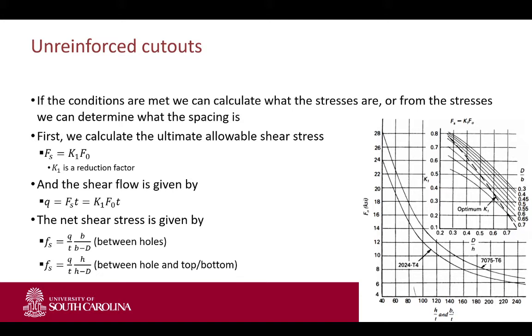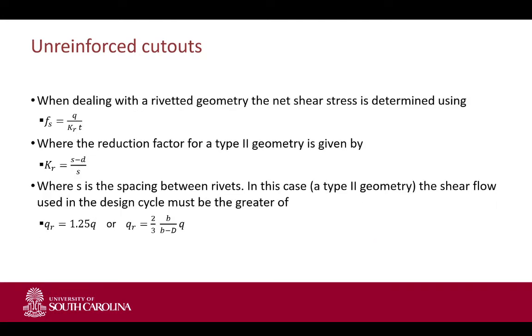Okay. And then you can also see how the stress concentration affects your shear flow, and based on your shear flow, the net shear stress. In this case, they use F, and I maintained the same variables they use in the NASA report. So you can see how the shear stress between the holes, and between the hole on top and bottom, varies based on the hole diameter, the height, and the thickness. And of course, if you have riveted cutouts, you have to take into account the stress concentration on a rivet. So again, it's the same procedure that you have to apply over and over again.